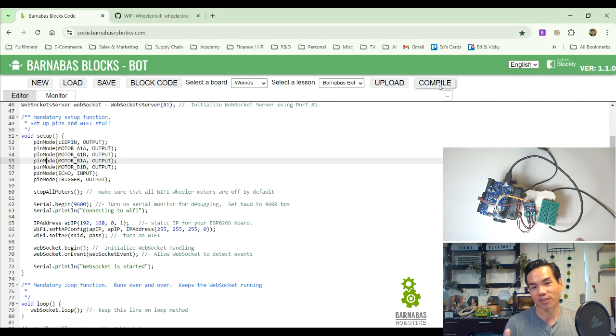A lot of times those only have power. So if you use one of those cables, you might see this light turn on because you got power through your computer to this board. But when you try to upload or send communication, it won't work, and you'll be pulling your hair out. Why is it not working? Check your USB cord.